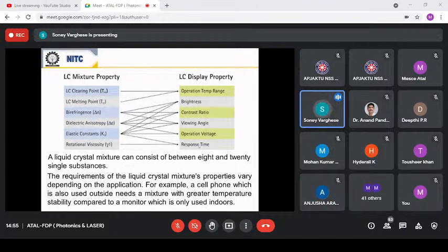That depends on the interaction of the molecule with other molecules, viscosity, and how fast it can move, because this is a thin film of material. When you apply an electric field locally, that molecule has to twist or move, so how fast it can move relates to the elastic constants, right? Then the rotational viscosity of the material is also related to response time.